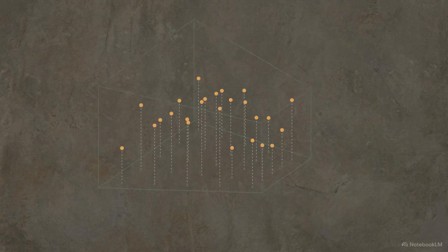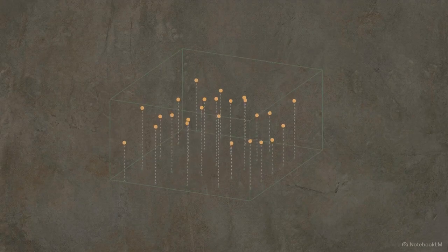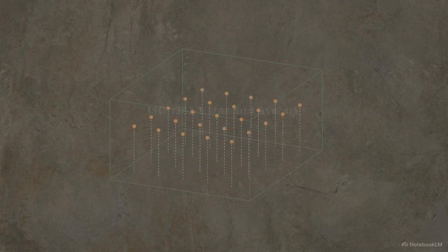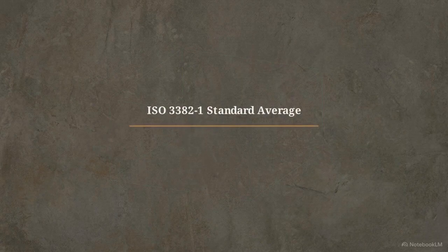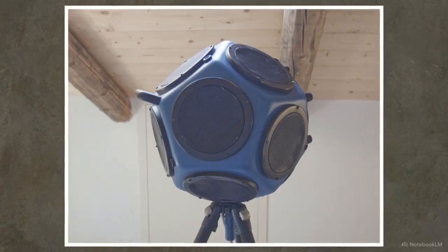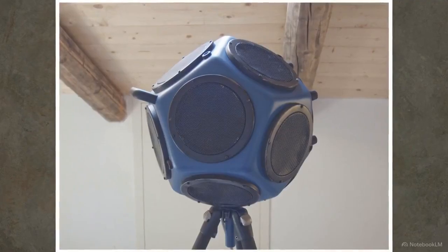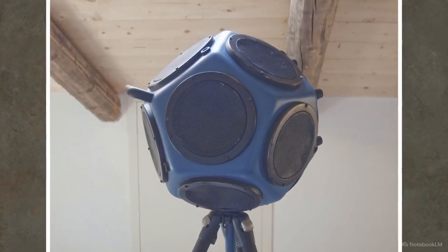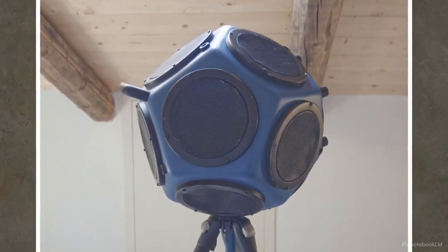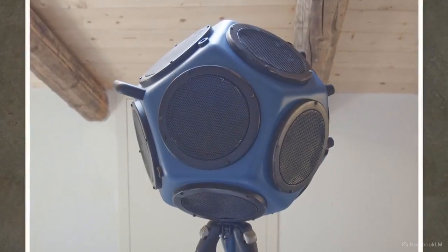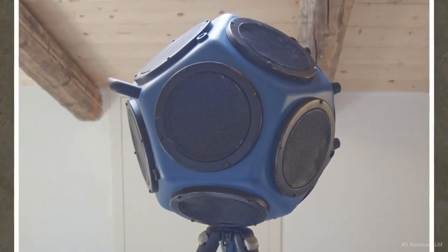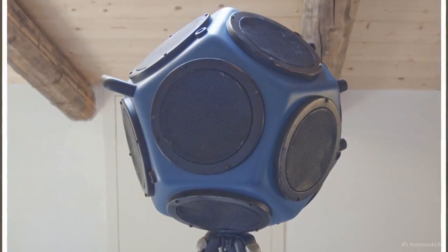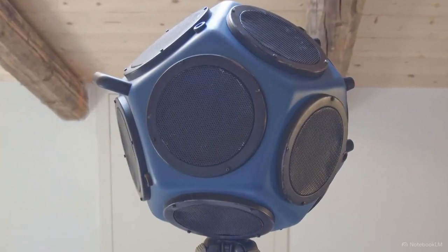Sound must reverberate evenly, so acoustic measurements remain the same anywhere in the room. For this to exist, an environment must be large and uniform, producing a sufficient density of acoustic modes, like contemporary concert halls. To test these spaces, engineers place microphones at various points and emit frequency sweeps using an omnidirectional source, like a dodecahedron speaker. They record data from multiple positions, averaging them into a single representative metric for the room.